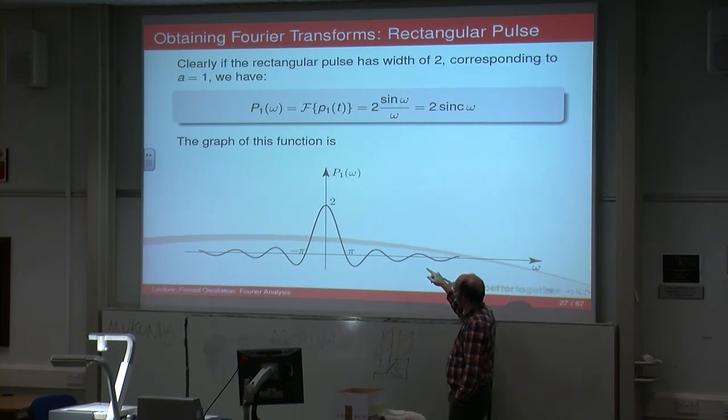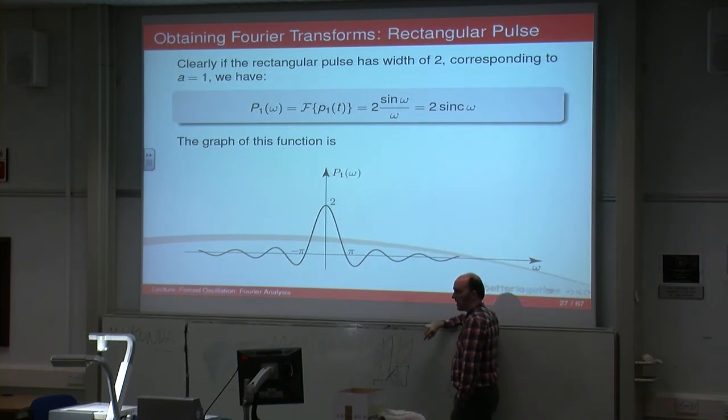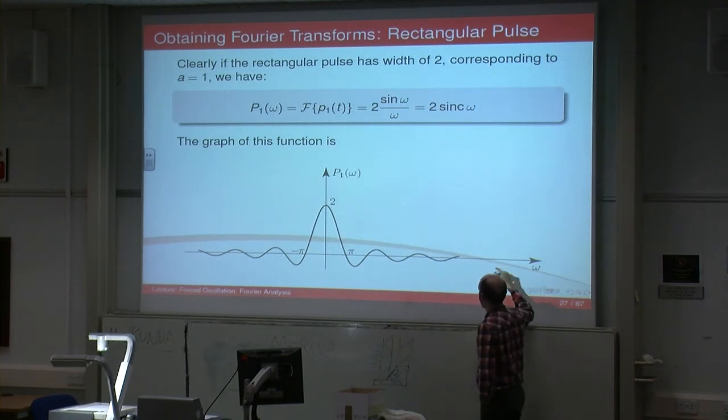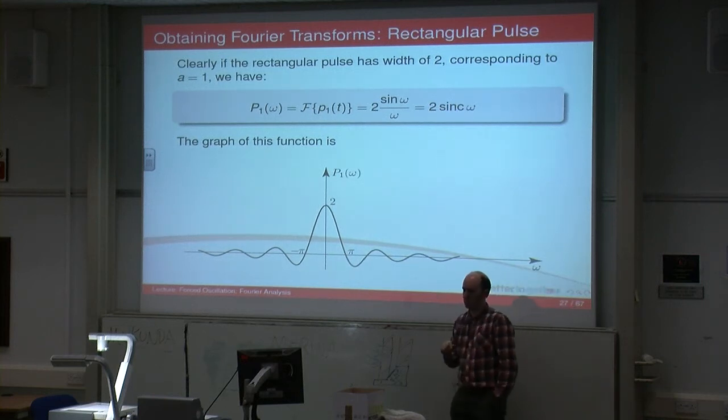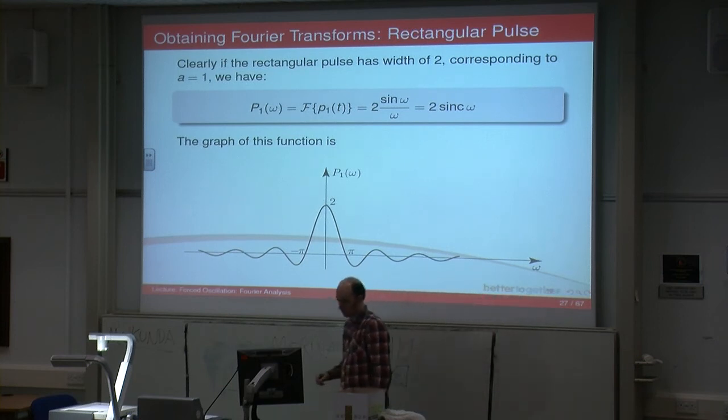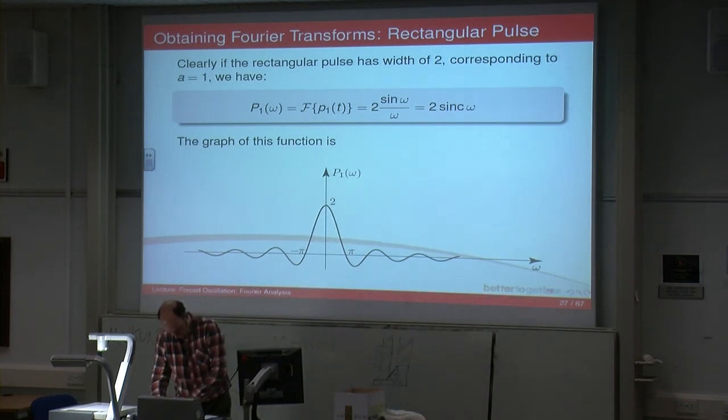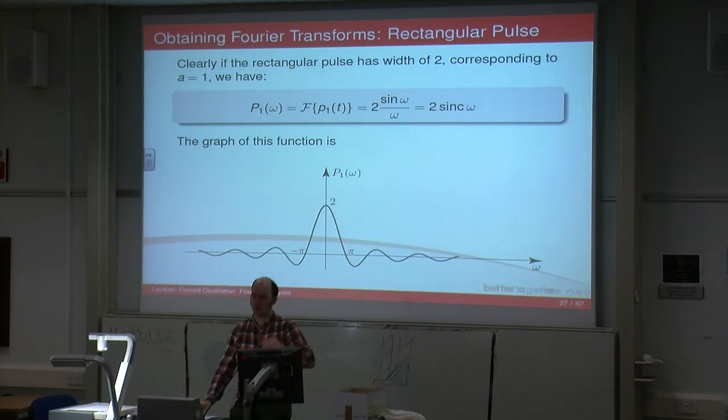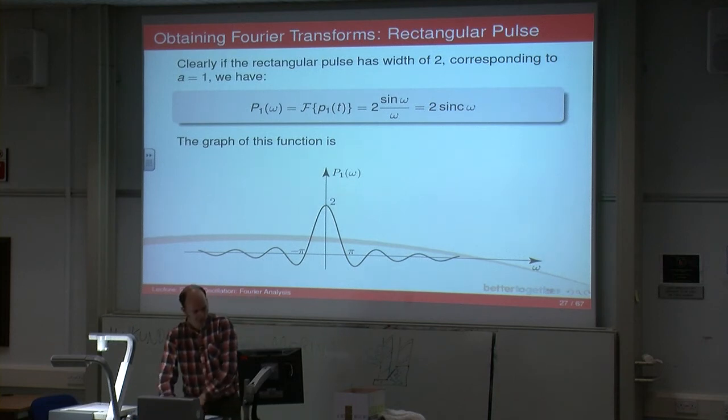So the Fourier transform, P of omega, of a rectangular force, a step force that returns back to 0, gives you a sinc function. So there's an example. Like I said, we saw that before: as the period goes to infinity, you end up getting this sinc function as the frequency response of that system.